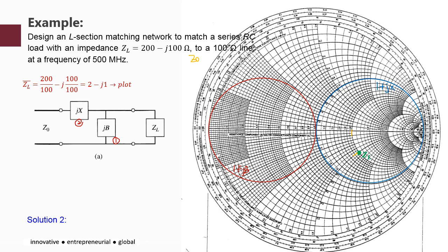Right, so in order to have the admittance, as discussed earlier, the admittance is basically the translation, or the opposite, of your ZL. So you draw your SWR circle and get your admittance YL. Okay, so your YL in this case is 0.38 plus J0.2.